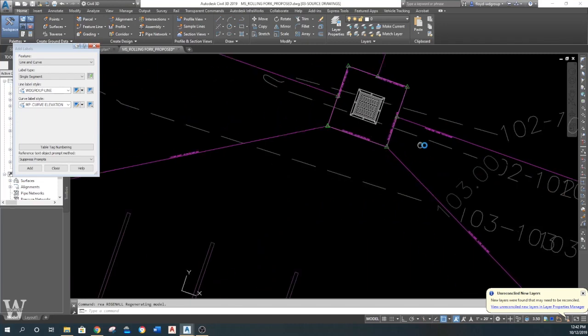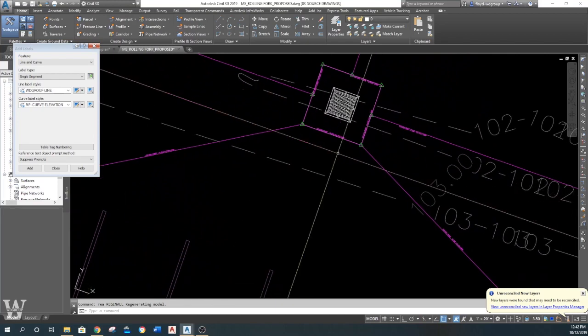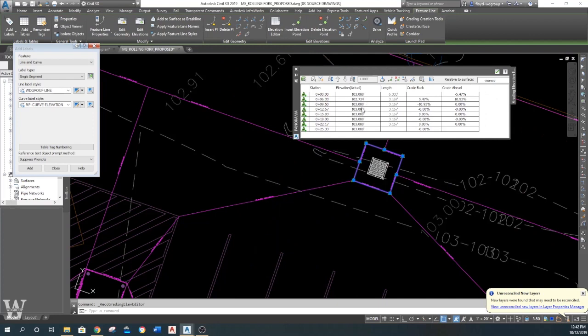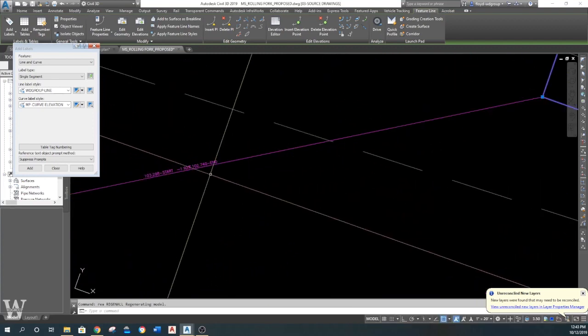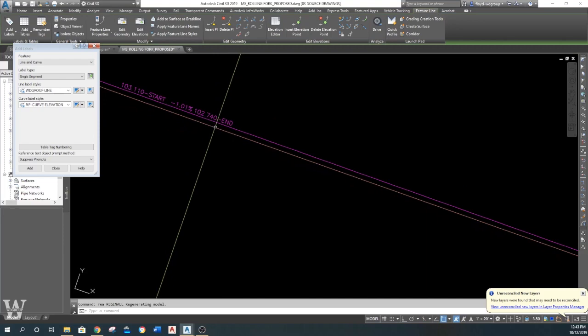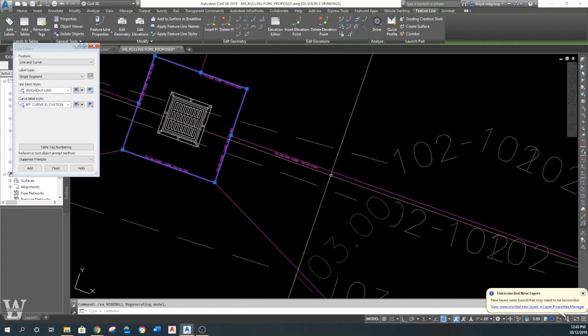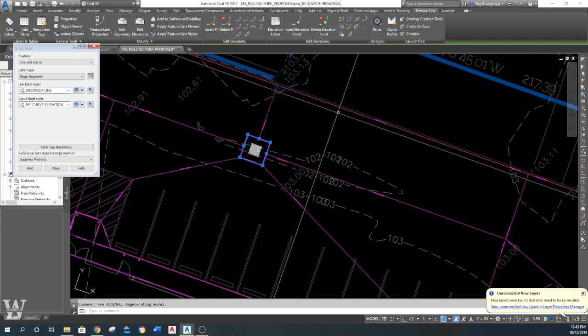So that's still below 0.75. We didn't change it. 102.734. So what we're going to do here is pick this one up and do it like this. 102.74. Let our elevation editor change all those. Regen, so it picks them up. 1.9%, 1% that way. I'm worried about this one right here. It's 3.29. It's a little high right there. 0.6. So that works right there.